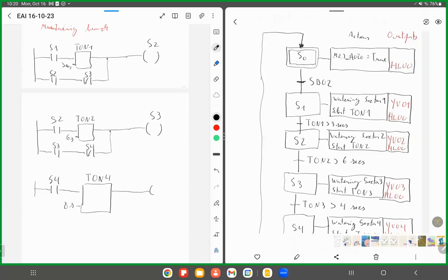And I'm going to activate some internal variable. Let's call it M10.0, and 8 seconds, something like this. Okay, just a name. It's an internal variable. That's why it's an internal Boolean variable in memory position M10.0. So this is an auxiliary branch, an auxiliary network.